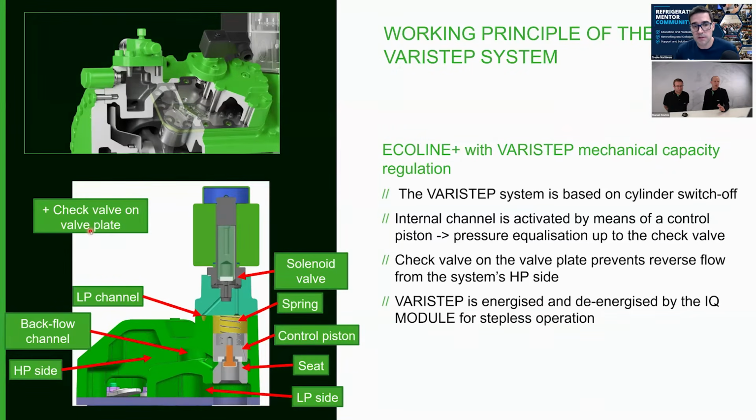Yeah, that is something I will come back to later on, where we also have our application limits. Within what we publish, this is tested and verified, but you are completely right. At lower pressure ratios, at some point the valve plates no longer function properly. A compressor is not a pump able to do really low pressure ratios. That is why we also publish where it can be used and where it should not be used. I love it. Okay, sorry, I'll come back to questions.